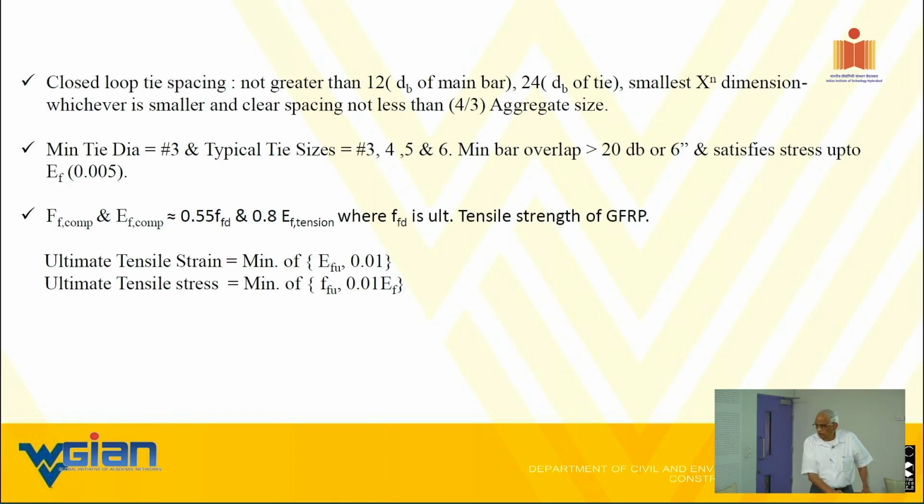So I don't know how you place a gauge. What we did, we leave a little styrofoam plug, and then we have a gauge, and then we bond it. After concrete is poured, we dig it out and attach it to the wire. Now we have wireless gauges too.